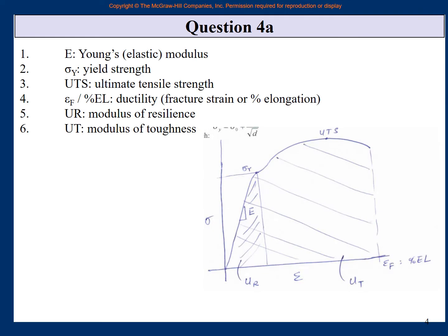So I am showing you the solution now. This is my hand-drawn rough graph, right? Sigma, the stress, on one side, and strain on the other side, and roughly this type of graph is there. So this is a rough stress-strain graph. Then on this graph, here I show the slope E, here I show the point sigma y, here I show the point UTS.